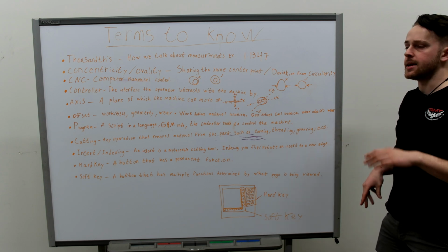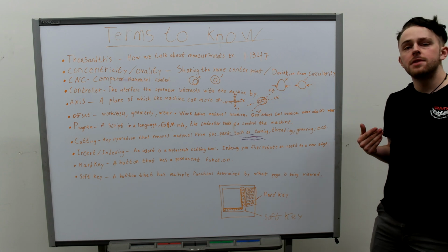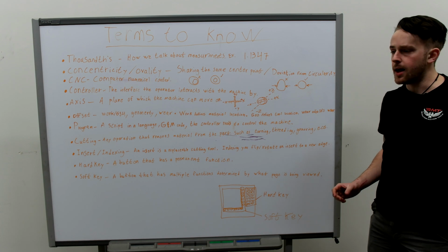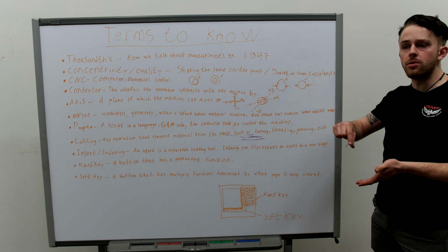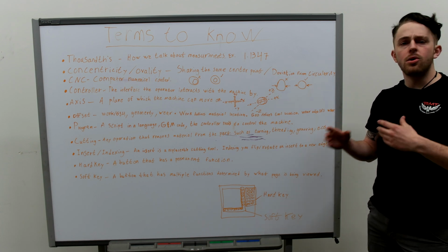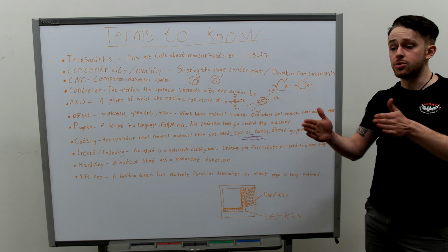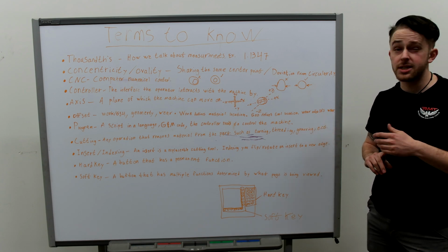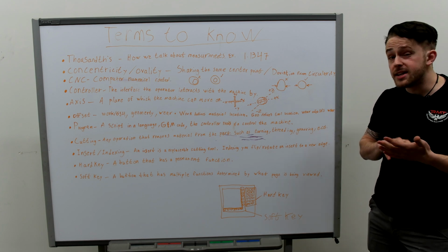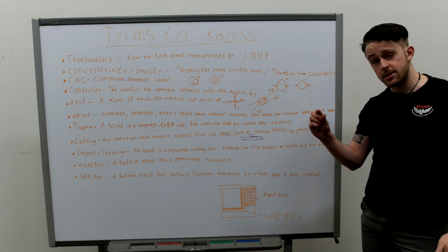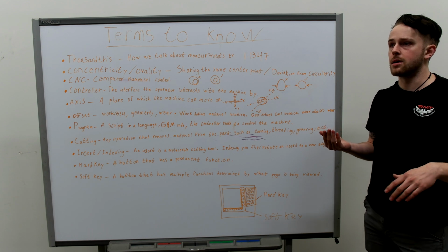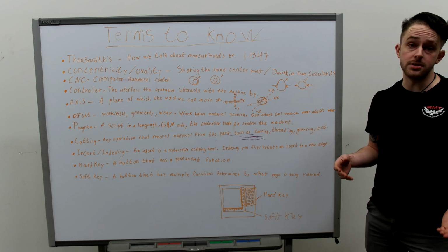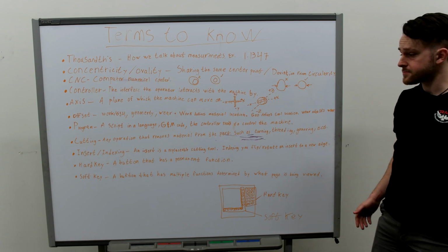And indexing that insert looks a little bit different for each and every insert, depending on the type, but essentially what that means is rotating it or flipping it over or something like that to get it to a new cutting edge. Commonly, threading inserts typically have about 3 different cutting edges per insert, whereas our CNMG turning inserts typically have about 4 edges that you can utilize.